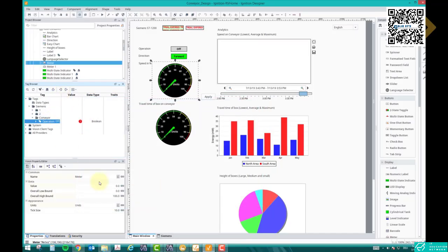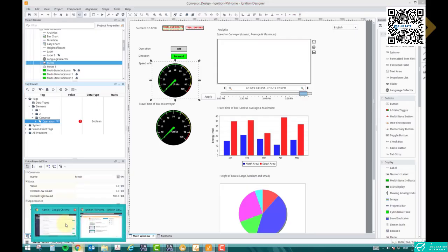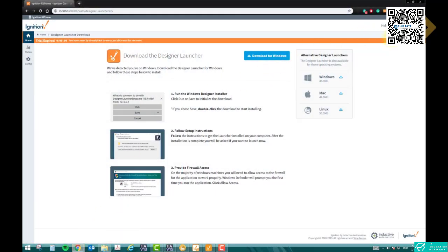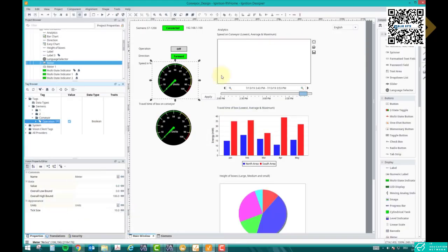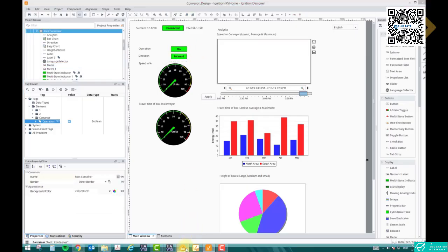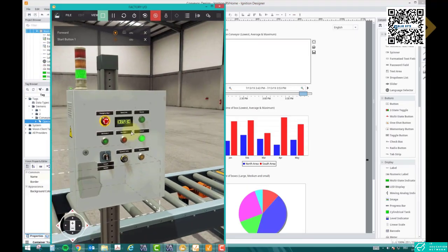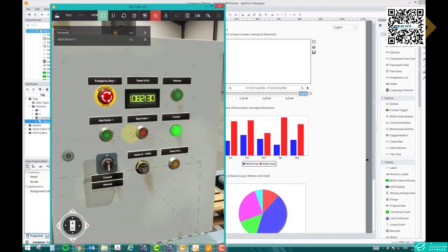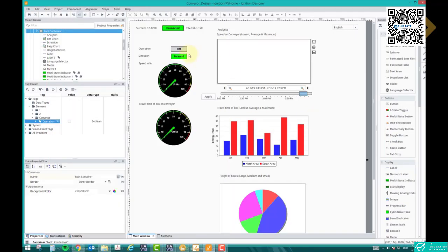And this is showing red because our PLC, our SCADA needs to be reset. Now it's reset. So this tag is okay. So operation tags go here. Right now it shows it's on because the motor is running. Okay. If I stop it, this should be off. You can also show operation stop or motor running, motor off. It's up to you. You can change the text, no problem.